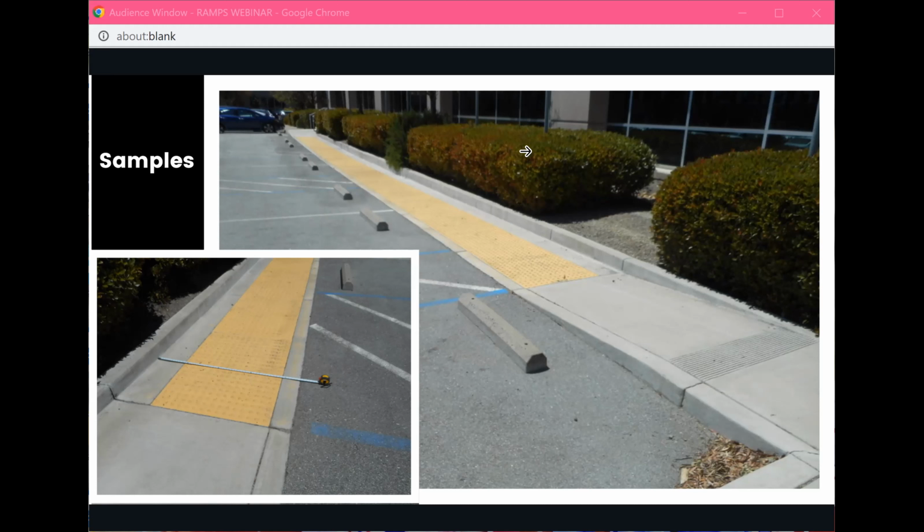This is pretty much what we're doing in parking garages, where we would have 36-inch wide detectable warnings parallel with the stall run of the stalls. And because it's inside a garage, we would only have a 36-inch walkway in parallel with those detectables. Pretty much like what you had here, but just an extra couple of feet for concrete. Right, that's what we're usually typically showing.